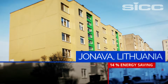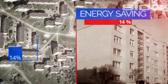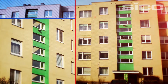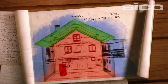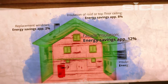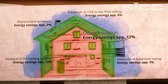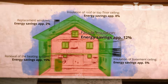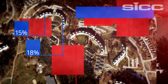At a building in Jonava, Lithuania, the same professionally applied Thermo-Shield facade coating led to an energy saving of more than 14%. The savings that may be realized with an external insulation bonding system vary widely, depending upon the provider and those interested. The independent German institute Heizspiegel comes with current comparison values, with a saving potential of only 12% in the case of afterwards installed insulation systems. Sources near the producers speak of 20% and more.